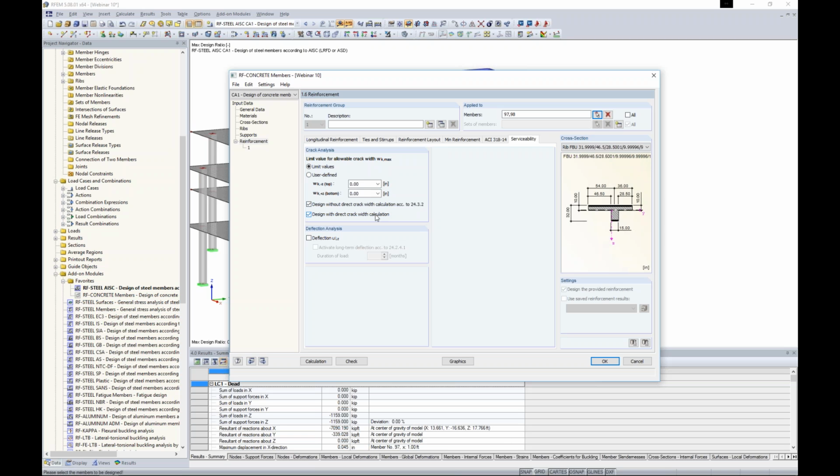Now we can apply the Gergely and Lutz equation to come up with a theoretical equation to calculate the crack width within the member and compare it to some limiting values here. If we want to do so, we have some suggestions here from the ACI committee. Maybe we will choose 0.02 because our structure is in a very dry environment. So now we'll check according to both crack width and spacing requirements for serviceability.